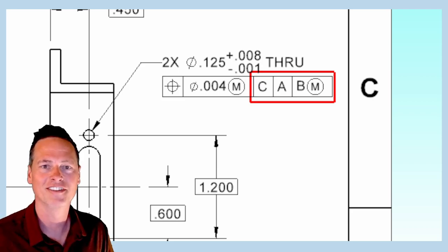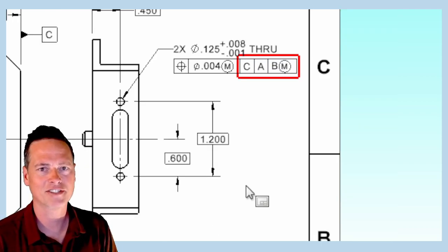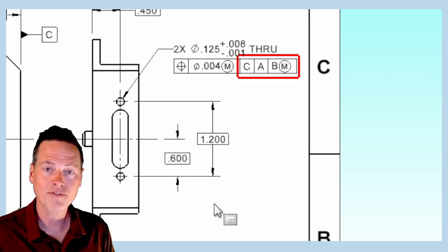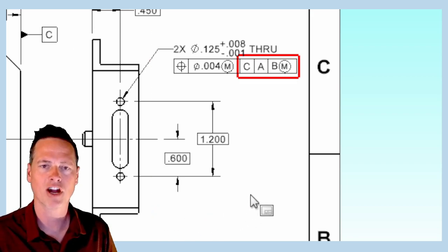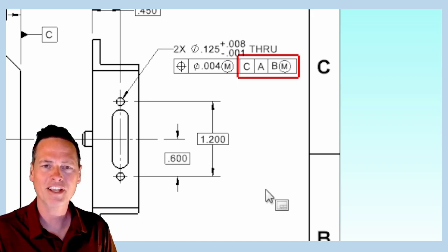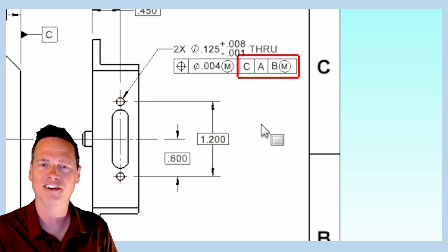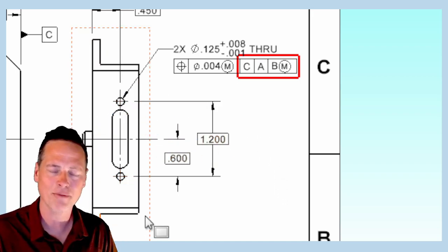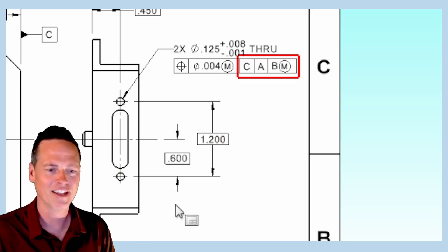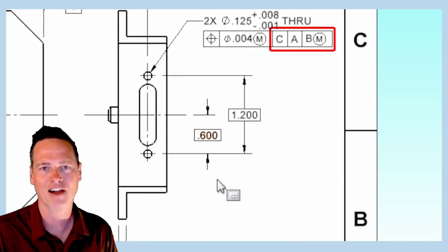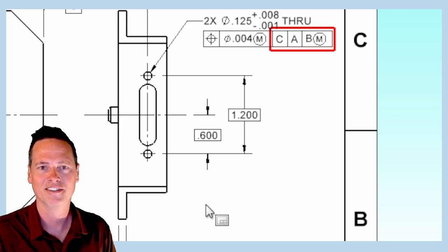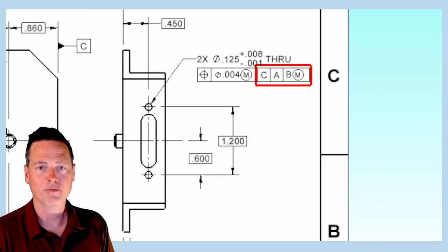It's bogus. What do we think is the part that attaches to these holes? I can believe that it would use the datum C feature as a primary datum. But what I can't believe is that whatever attaches here is going to pick up the entire datum A feature and locate off it. And I definitely don't believe it's going to locate off of the datum B features. And a call out like this could become needlessly difficult in inspection.